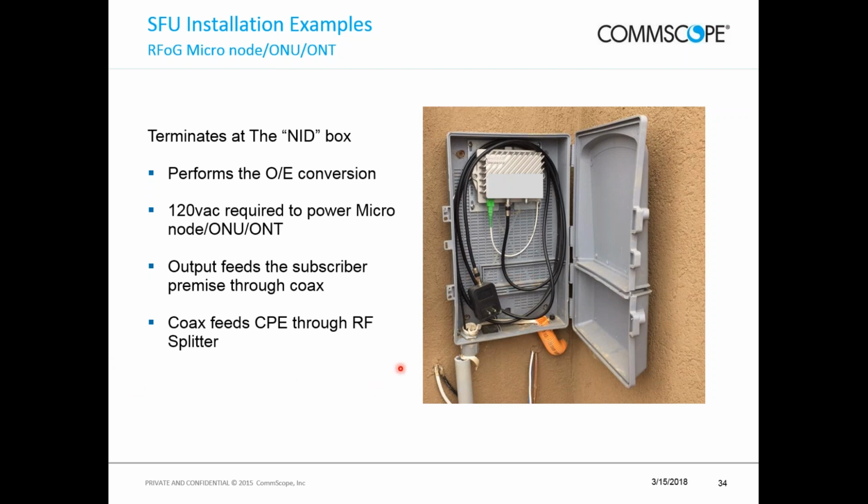Okay. Another thing. Go ahead. A person on the call has asked, is this 900 micron fiber, the drop fiber? Well, inside the 3mm jacket, it's 900 micron. And then you'll knock that off, and then you'll reveal the 250 micron, and then that's where you start preparing your fiber cable to connectorize it, if you will. But yeah, there is a 900 micron coating or jacketing inside that 3mm.